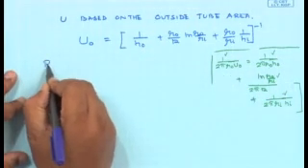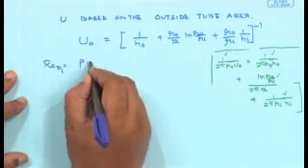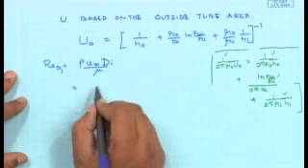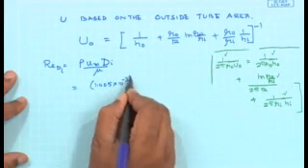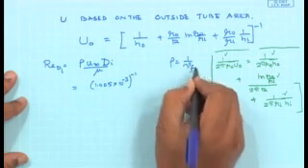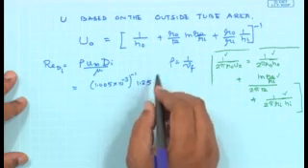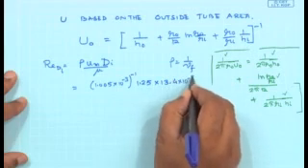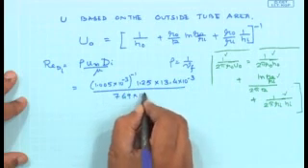In here we know that the Reynolds number based on diameter, and this is the inner diameter, would be rho um di by mu. So when you plug in the values, rho is simply 1 by Vf, which is 1.005 into 10 to the power minus 3 to the power minus 1, and the velocity is known over here, 1.25, and di is 13.4 into 10 to the power minus 3, and the viscosity mu is 769 into 10 to the power minus 6.